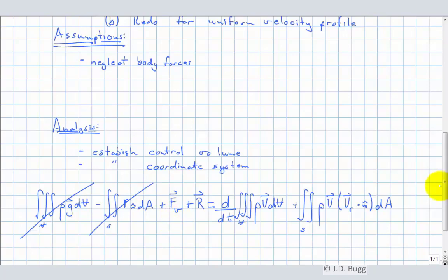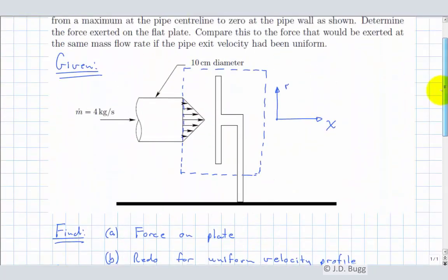Next, viscous forces. So again, viscous forces are due to force produced by fluid shear on the control surface. So we're only again worried about what's happening on the surface. Well, here we have an inlet, of course. Water's flying in here, but the water is just moving perpendicular to the surface. It's not moving parallel to the surface, so it can't produce a shear force on the surface. So there's no viscous force here.